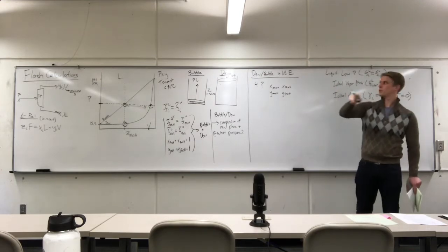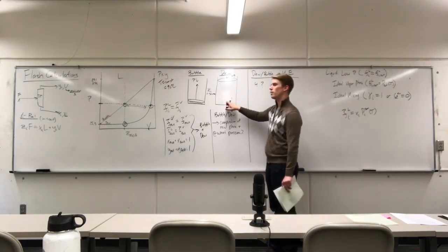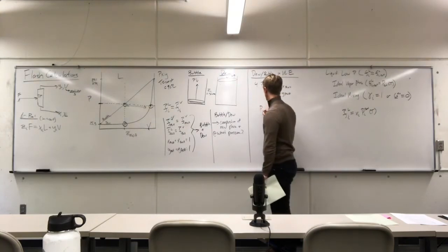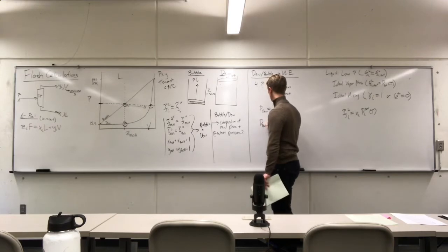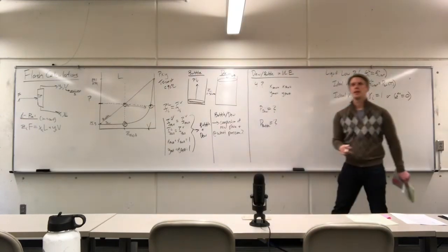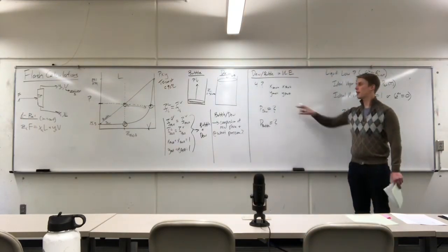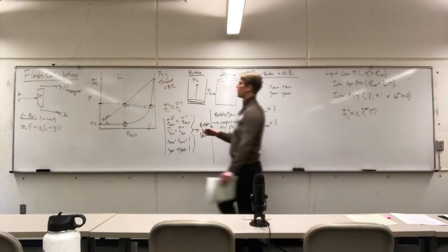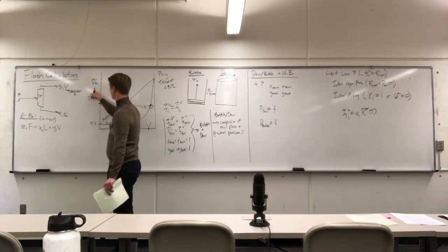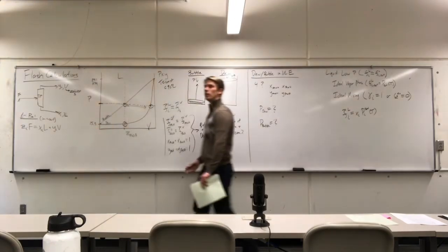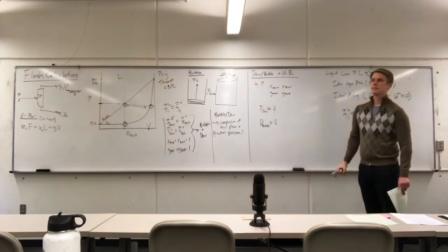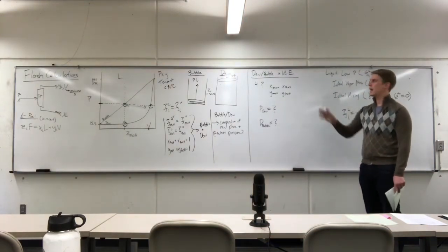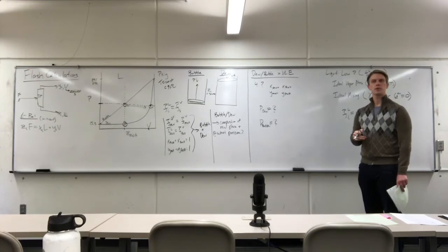So front 2 rows, you're doing derive me an expression for pressure of the dew is equal to blank. For the back 2 rows, pressure of the bubble is equal to blank. And then I also want to know what is the composition of the new phase that forms. This is for a 50-50 mixture. You're provided the pure fluid vapor pressures, 251 and 15.3. Temperature doesn't matter. Well, it's 90, but I've already used that information to give you the vapor pressures.